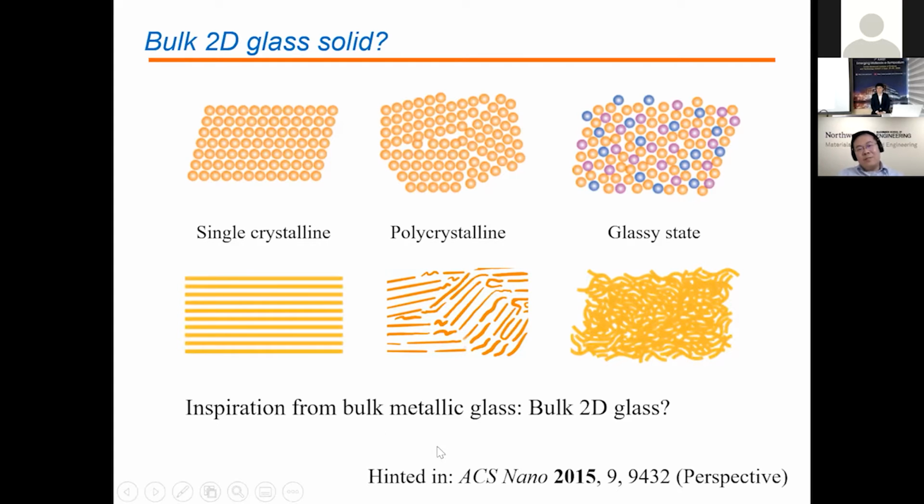But if you look at a bulk solid, it is not going to be a single crystalline solid. And it is usually made by densification and pyrolysis. So what you have is these different crystalline domains, but they are going to be jammed up together. And in between, there's going to be some disordered connectors or much weaker connectors.